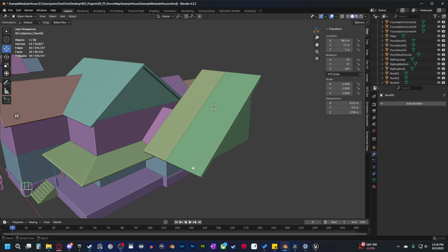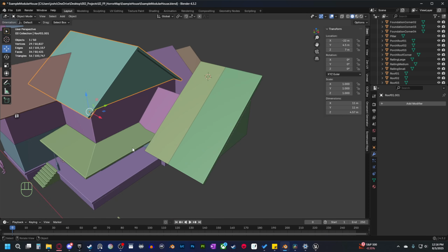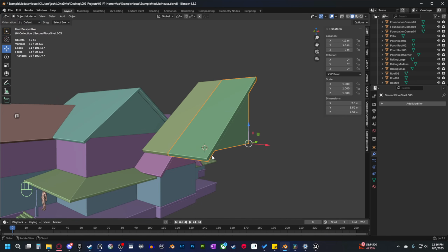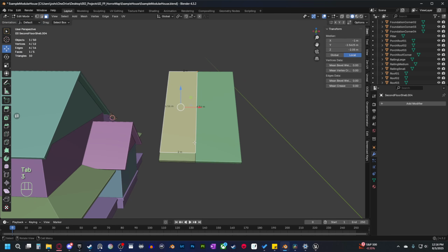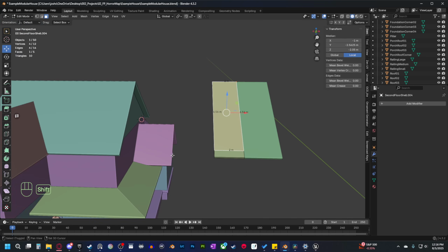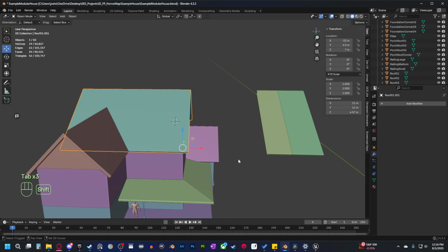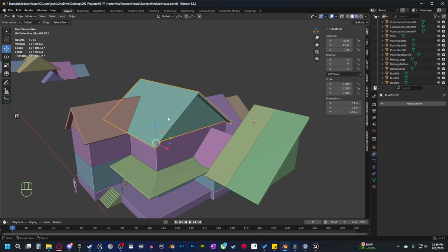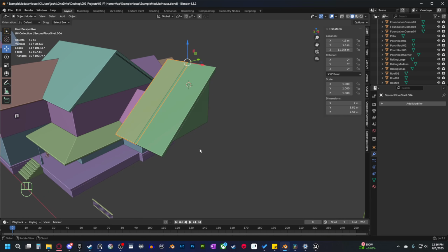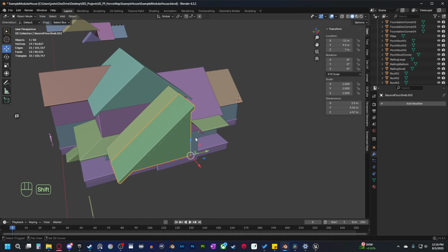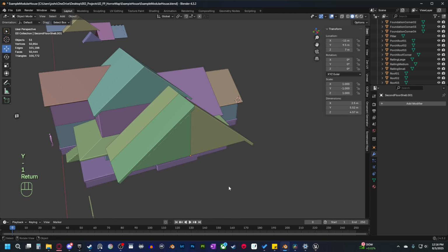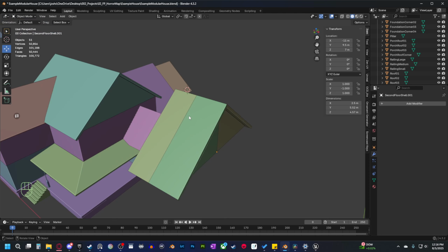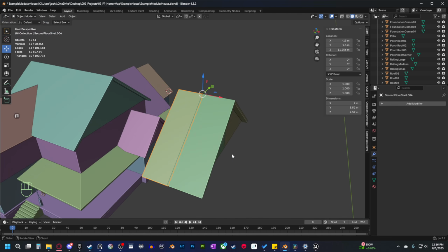I did start to create pieces, like for this piece right here. I just created this one piece here, and then this is a 2 meter in length piece this way. You could basically recreate this entire thing from these 2 pieces. To create this opposite side, you could just duplicate this, scale on the Y -1, and then you would get that. Then you could flip these around for the back and place these pieces in between.